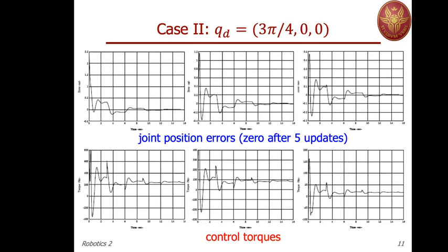we have to overcome, let's say, this straight arm configuration on the horizontal line, which is in fact the one where the gravity load is the maximum. So we have to overcome this maximum gravity load configuration in order to reach the 135 degrees of joint 1 with respect to the downward vertical, and again with the second and third link straight.